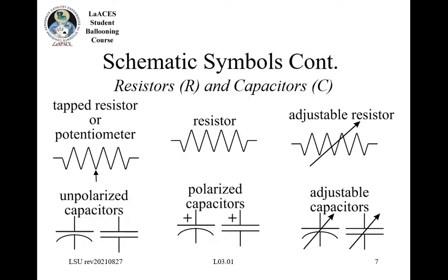So moving on, Josh told you a little bit last time about resistors and capacitors, and I think some of these symbols were on there, but this is the typical schematic symbol for a resistor. Okay, and then you have different types though. There are some resistors that can be adjusted, such as a potentiometer. You can often see symbols like this, but more common is this one over here with the arrow going through it. Okay, and that just tells you that in that circuit, that resistance can change by some mechanism. And usually it's like a small set screw that you can change, but there's different ways.